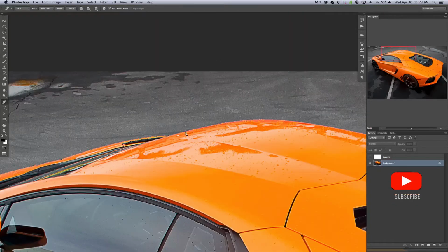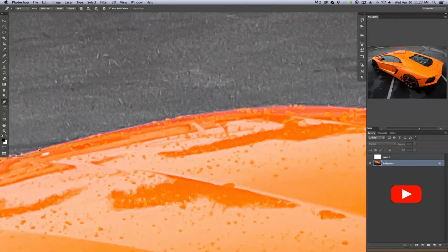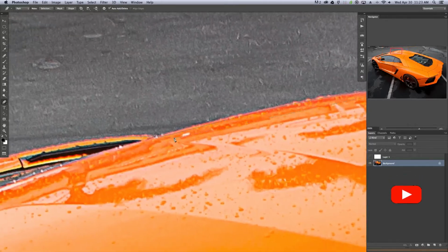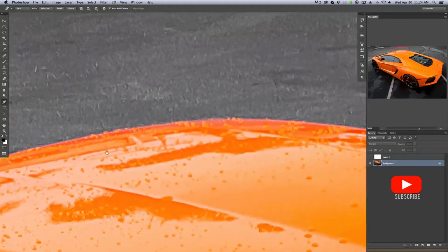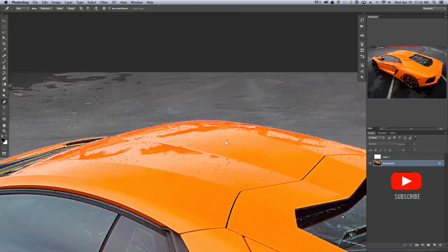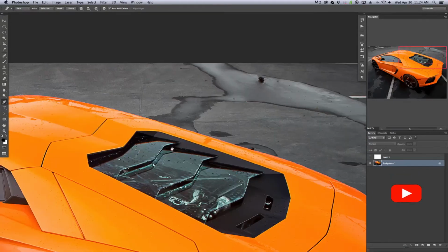Great. So now we're going to come up this way here, and I'm going to stop right about here. Hold again, Control or Command. All right, and you can see this one tried to keep my curve tangent. So I'm going to hold the Alt or the Option key now and bring this point back up that way. So it's not trying to go tangent to this curve. It's just going to allow me to do a non-tangent or non-continuous curve. I'm not sure if I'm using the correct math term here, but you get the idea.